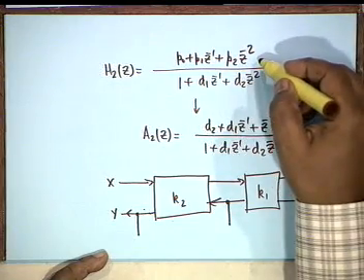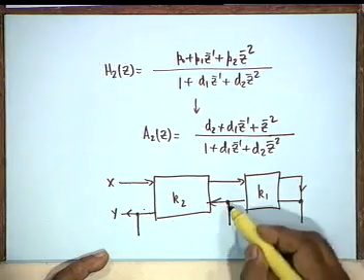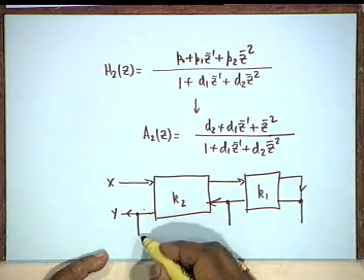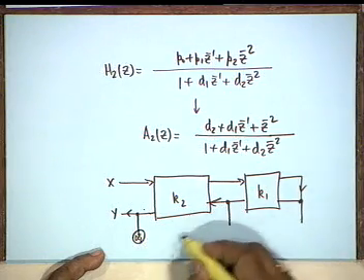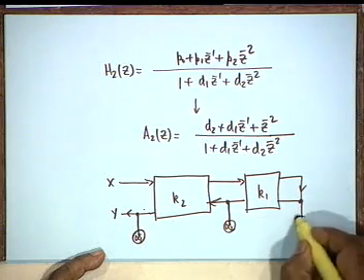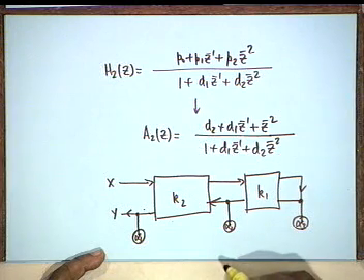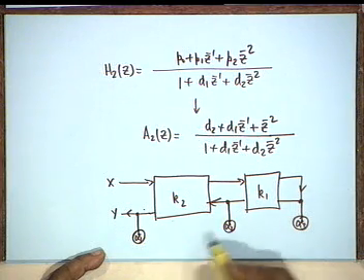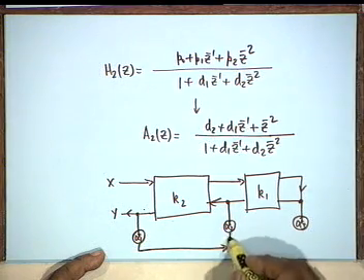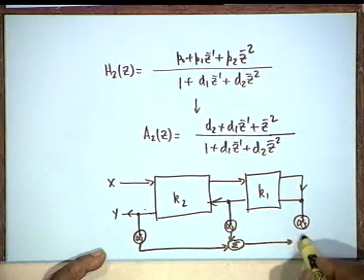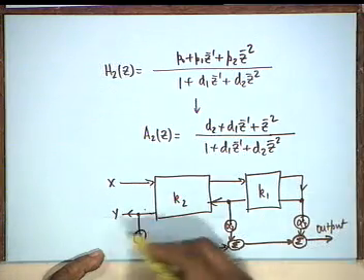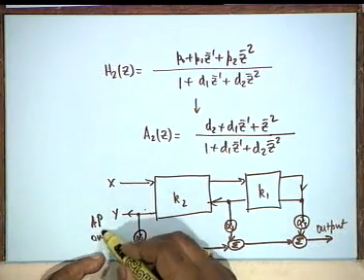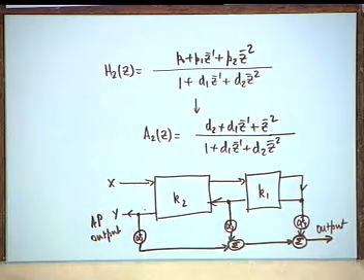In order to get a general filter, tap the outputs from the lower lines and weight them, that is, multiply this by alpha 1, this by alpha 2 and this by alpha 3 and add them together. Okay? Add them together. This is the philosophy that is followed, and this is now my output. This is all pass output and the required output is here.